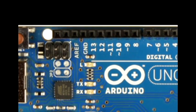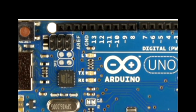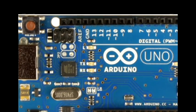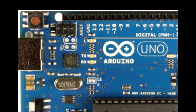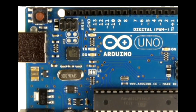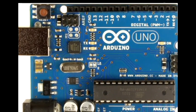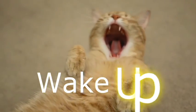Since these input pins have extremely small demands on the circuit that they are sampling, it is equivalent to a series resistor of 100 megohm in front of the pin. It takes very little current to move the input pin from one state to another, and this can make the pins useful for such tasks as implementing a capacitive touch sensor, reading an LED as a photodiode, or reading an analog sensor with a scheme such as RC time.